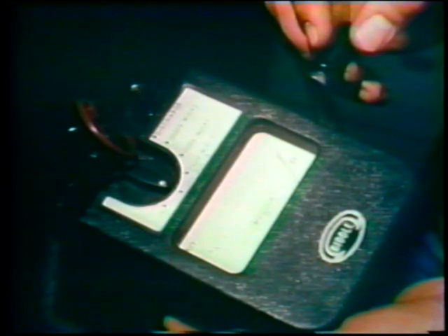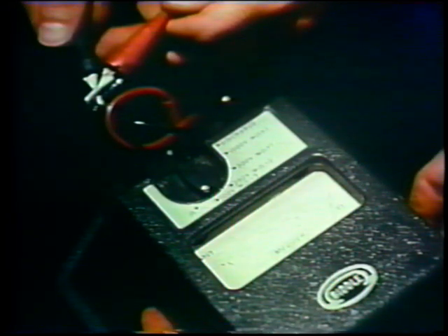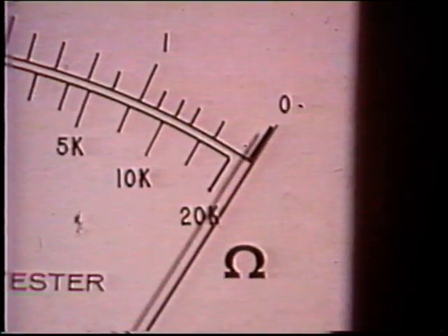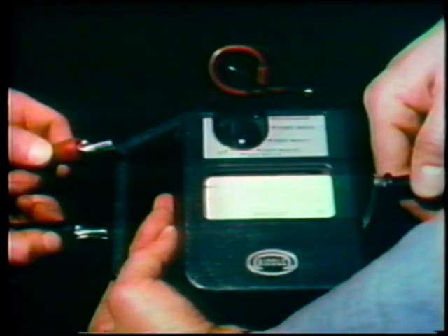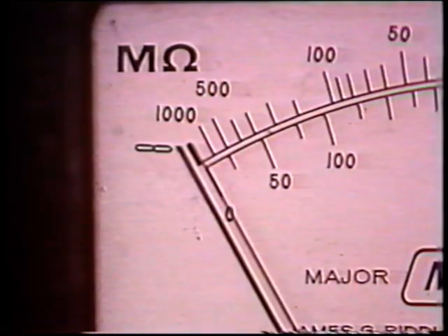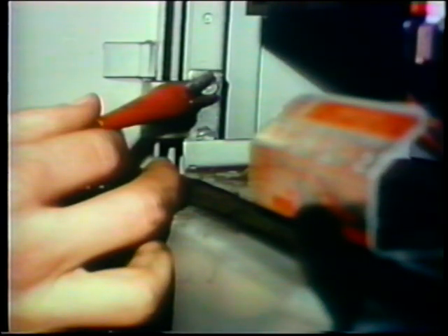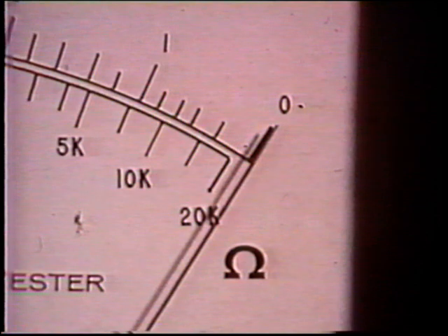Before using the megohm meter, it must be tested. This is done by clipping the two probes together and operating the megohm meter to see if the meter will indicate zero resistance. Then separate the probes and operate the megohm meter to see if the meter will read infinite resistance. Next, connect both probes to ground and operate the megohm meter to see if the meter will register zero resistance. A zero resistance reading indicates that the ground connection is good.